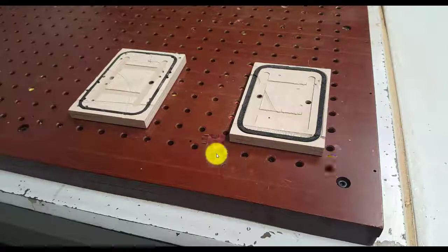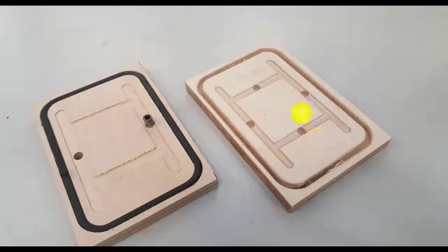And when those positioning pins are put in temporarily, you can align the workpiece with those pins, then pull them out afterwards after the suction and the compression has been applied. Here's a couple of the pods just before they've actually been fully prepared. You can see the holes drilled through. This little pipe just allows the suction to get up. That pipe sits down into one of the existing holes, and you can see here there's a deep groove removed for this rubber seal. You can buy those lengths of rubber seal, and as they become damaged, you feed them back into there just to make sure you get a very tight seal around the pod.